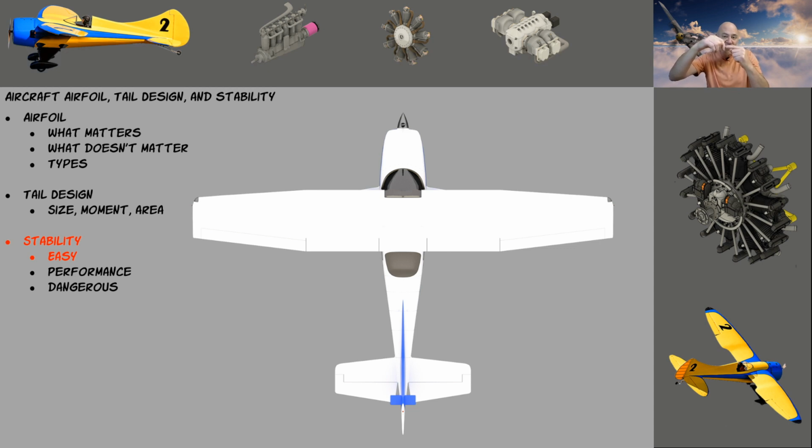I might move it in a little bit so that you get a little bit more throw or a little bit less throw. Me personally, I only like 20 degrees up and down on an elevator, unless it's aerobatic. Sometimes you can stall it. If you go to 45 degrees, chances are that elevator's not even really doing that much unless you're in a true hover mode. If you're flying through the air and you got 45 degrees of up elevator,